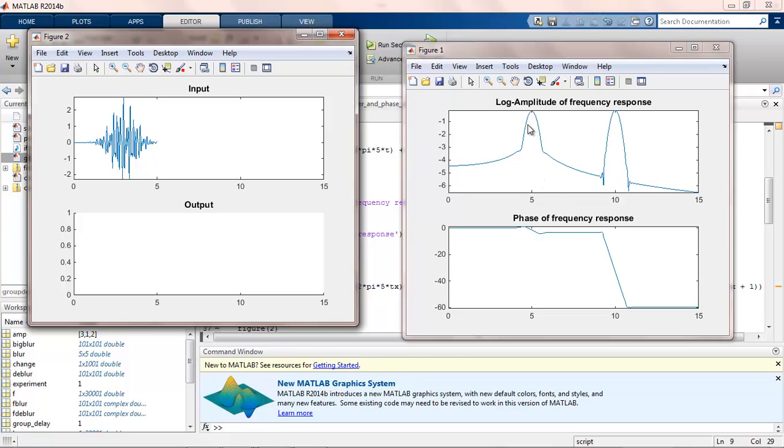Those should not be affected much by the filter in terms of magnitude. The frequency 7 should be basically eliminated. Okay? But there's one thing we can anticipate from the phase. Notice that the derivatives of the phase are different for the 5 frequency and the 10. I designed those to be different. So according to our calculation, these should have different group delays.